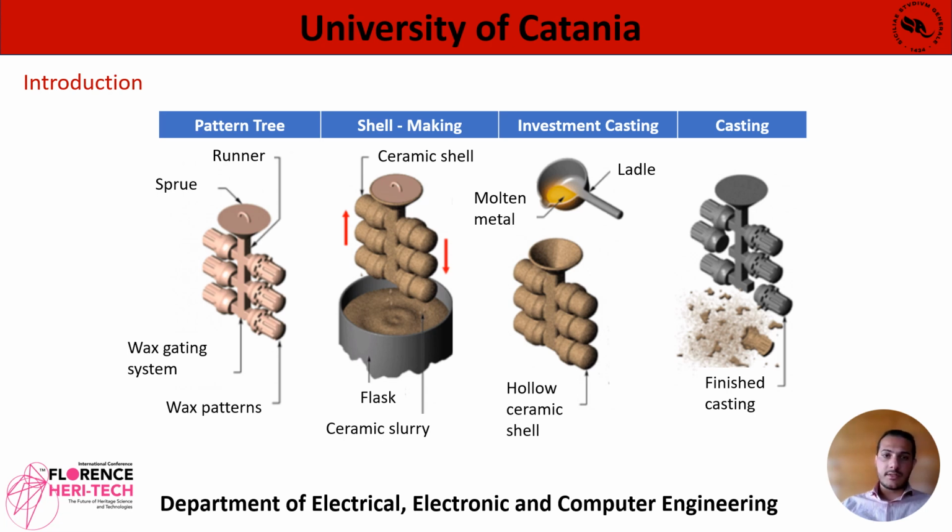Investment casting is a process based mainly on the lost wax casting technique and consists of a succession of highly specialized steps aimed at obtaining the required geometric and metallurgical properties. This method involves the use of a material with a low melting temperature, usually wax, to create the model. A mold made of refractory material is created around the wax, the characteristics of which must be such that it can withstand high temperatures and metallostatic forces.